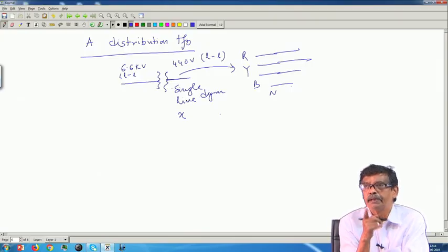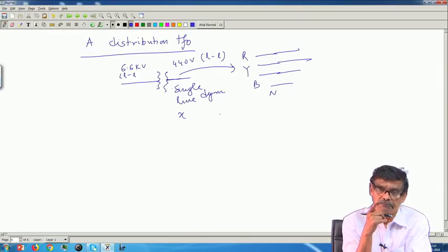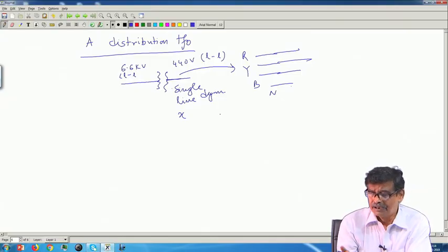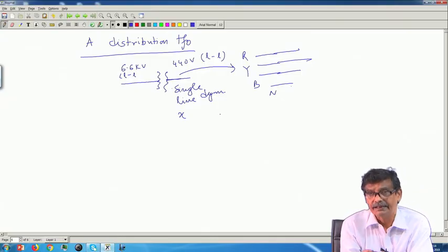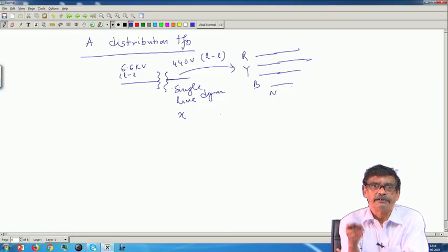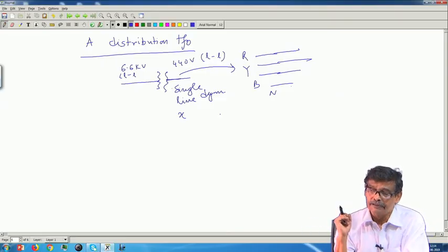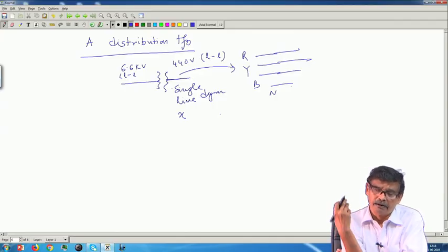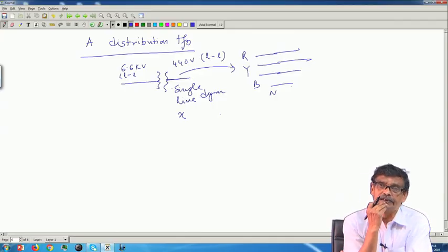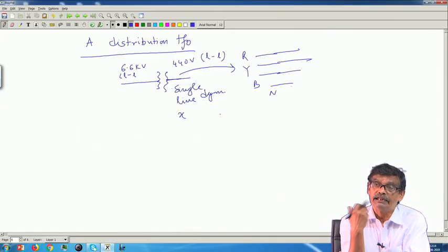That is, its maximum efficiency must occur at x equal to 1, that is at rated condition. But here is another extreme example, where a distribution transformer secondary supplies different consumers and the degree of loading on the transformer goes on changing and goes on changing wildly.